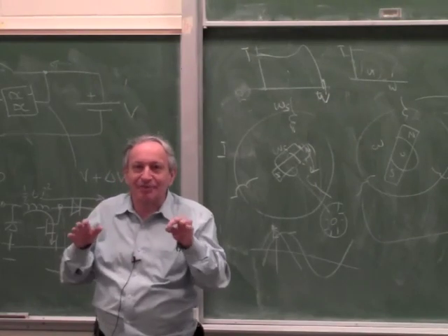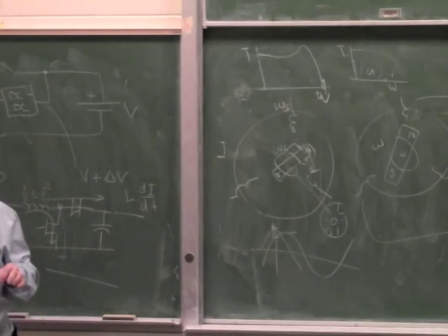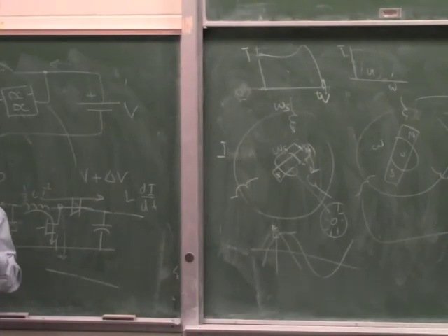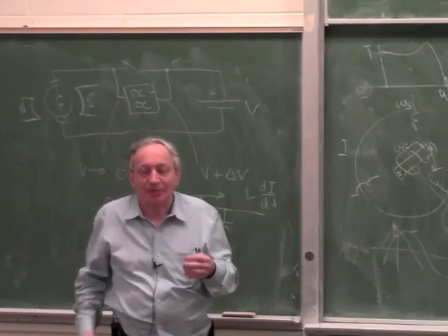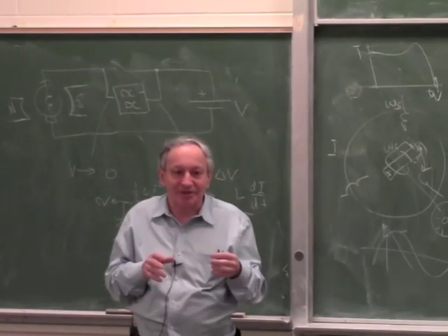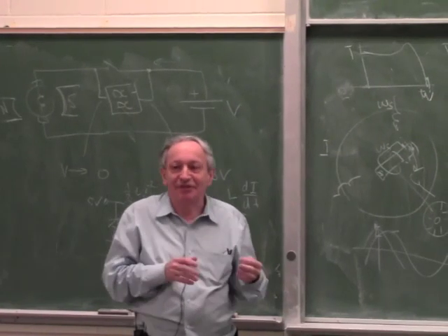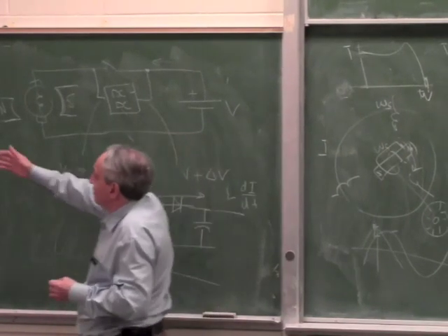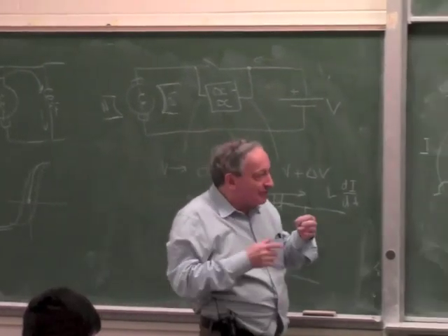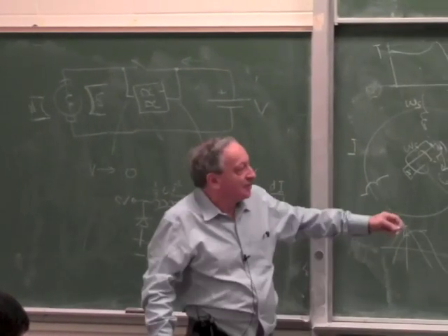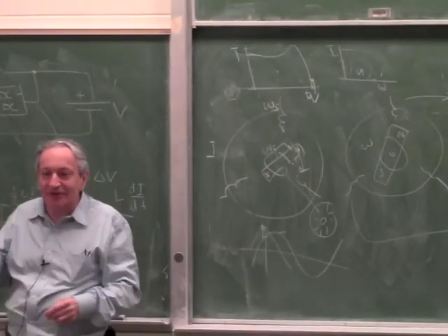I know I didn't spend enough time explaining it in detail, but it's way beyond the scope of the course. But what I wanted to show you is that you don't necessarily need a permanent magnet to make a generator. The generator can be self-excited by many different ideas, starting with this idea in DC motors, or starting with more sophisticated ideas of being ahead of the rotating field and feeding power back.